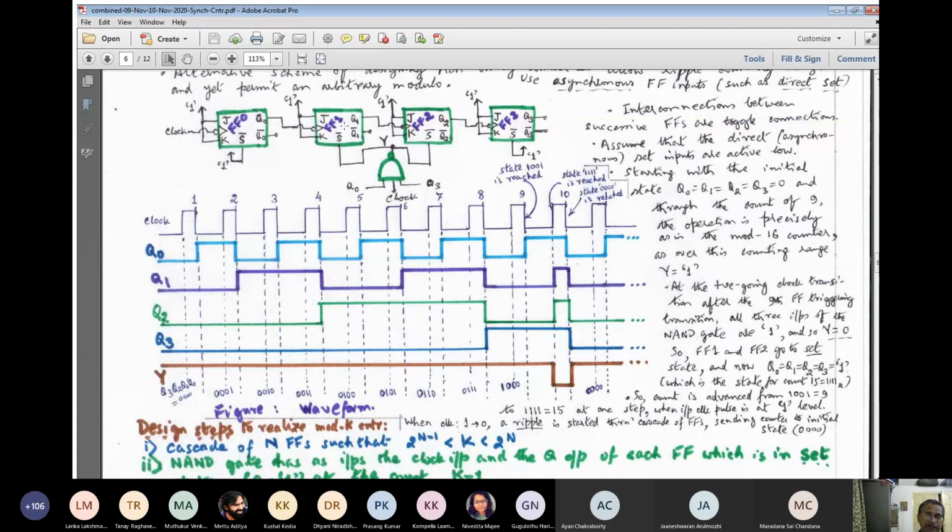That means when the strobe signal to read out the state of all one is necessary to be generated here, we have to add some more delay. That delay is nothing but adding the delay of 2 NAND gates in succession. And definitely we have to take care in designing the clock on time. Now again, as you are designing the sequential circuit, the length of the on time, the off time, and the period of the clock will be of utmost importance.